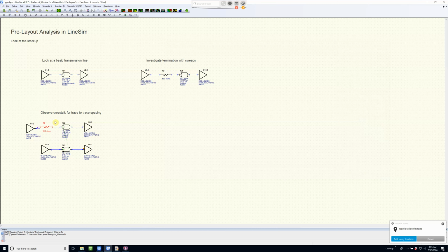So in the pre-layout analysis tool, you can answer several questions prior to even going to layout. Instead of entering your constraints by rules of thumb, you can actually analyze them and get exact values to provide constraints to the layout for a real constraint-driven layout.